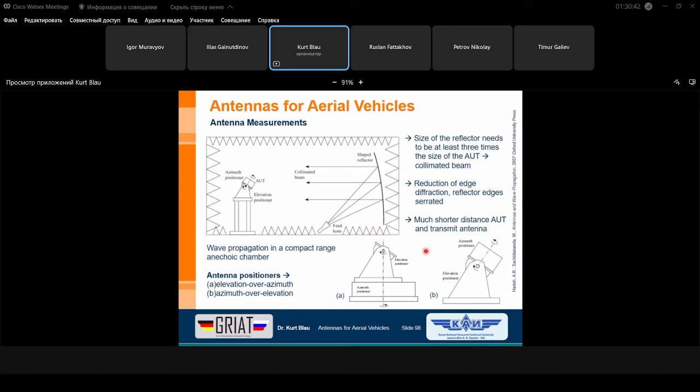In principle, every point. In practice, the scenario of the measurement is realized in such a way that you cannot use, let's say, a high density of measurement angles. Means you have to give the measurement engineer information that you want to have in elevation and in azimuth.